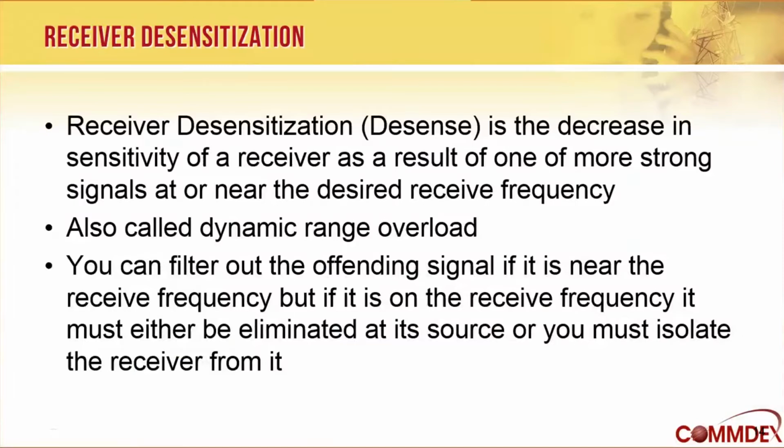You can filter it out if it's near the receive frequency, but if it's right on the receive frequency, you can't filter it out, so you have to go to the source and either eliminate the source or isolate yourself from the source.